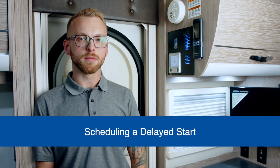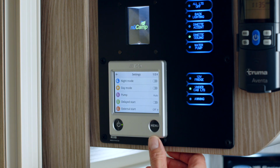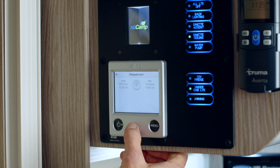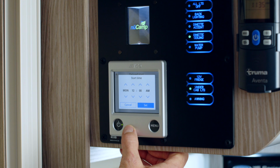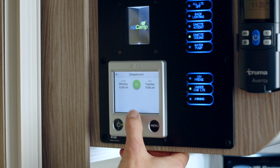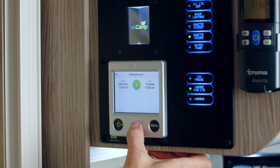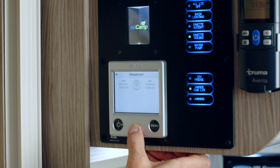The Alde 3030 controller will allow for a delayed system start. This is a great option if you know that you don't need heat at the beginning of your trip, but there may be some colder nights ahead. To begin a delayed system start, press the menu button at the bottom right corner of the screen. From here, you will select Delayed Start. Under this menu, we can select our start day and time, and our end day and time. We can also activate or deactivate the delayed start from this menu.